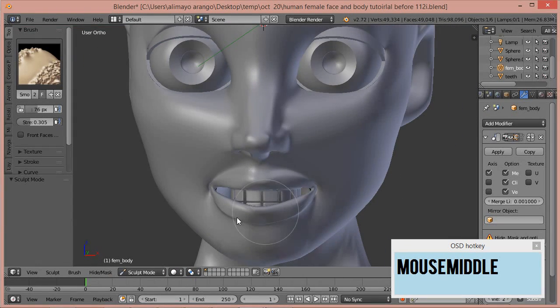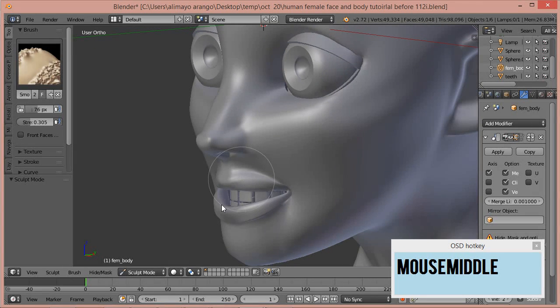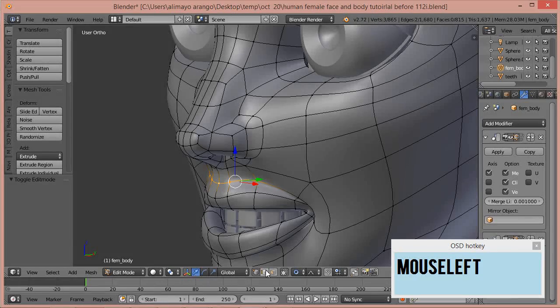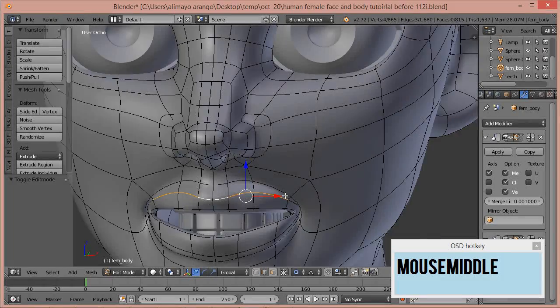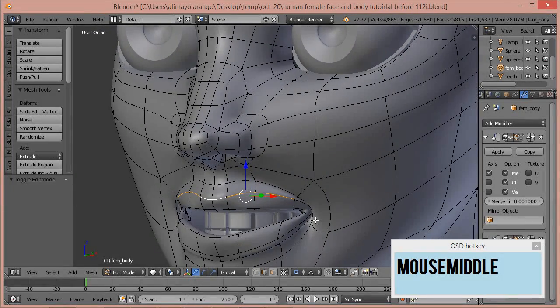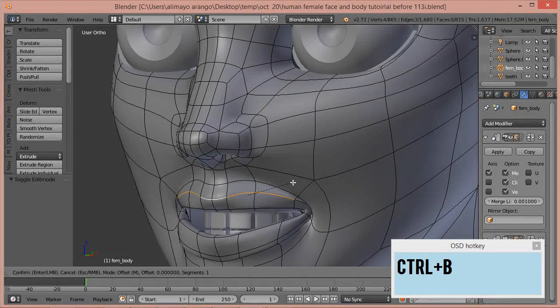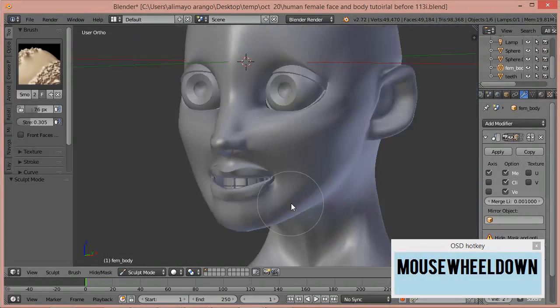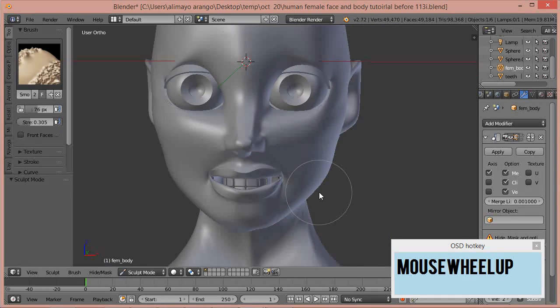You see, I pulled that up there, and it took away the kind of bulge of the lip. Just learned this trick. It's pretty cool. Or technique. You grab here, get that good old bevel tool. Grab here. Okay, and then you hit Control B. Just pull slightly. Go to sculpt, and now you can see we have a nice hard line right there.